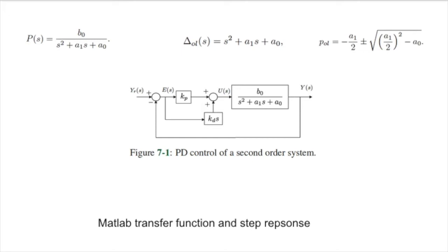Let's take a simple example. Let's say I have a plant here. I'm just discussing PD control for now, no integral. As I said, integral control is needed when there is a steady state error, so you first have to determine if there is one or not. If you remember from last class, there was a DC gain or final value.